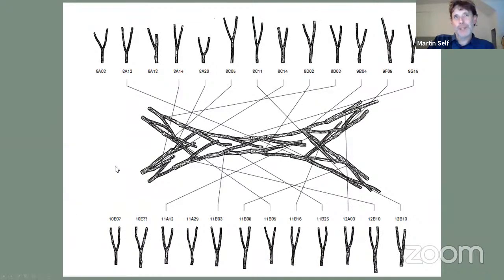I talked about it very briefly on this slide, and there's a whole presentation that explains what I summarised very quickly, particularly the work of one of the students, Zach, who set up a Galapagos solver. It takes the medial line geometries, the curved centerline of each element, and the target geometry for the truss, the ideal structural chord lines on which these pieces wanted to be deployed. It was done in Grasshopper, but tested through scripting.